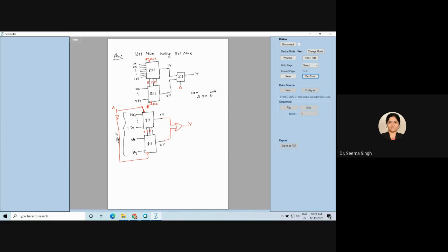For 0 to 7, 1Y is connected to the input. Without bothering about what is coming at 2Y, when it is not enabled, it will be 0. And if this is 0, Y will be equal to 1Y, right? If 1Y is 0, Y becomes 0. If 1Y is 1, Y becomes 1. So your second input becomes redundant in case of the OR gate if it is 0.